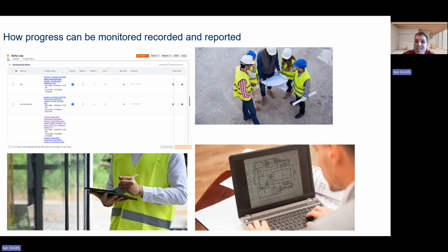I'll also carry out health and safety checks as part of our daily management of the site, reviewing accident data, reviewing risk assessments, and making sure any changes to the site, such as changes in machinery or changes in chemical products, have the correct control measures in place. Monitoring this health and safety performance helps maintain a safe working environment.